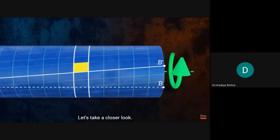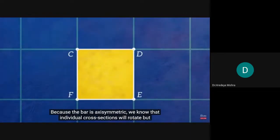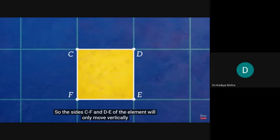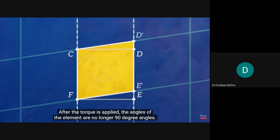Let's take a closer look. Because the bar is axis symmetric, we know that individual cross-sections will rotate but won't get distorted, so the sides CF and DE of the element will only move vertically along the lines shown here. After the torque is applied, the angles of the element are no longer 90-degree angles.